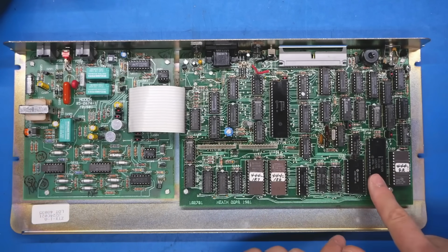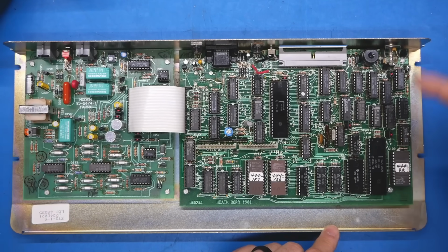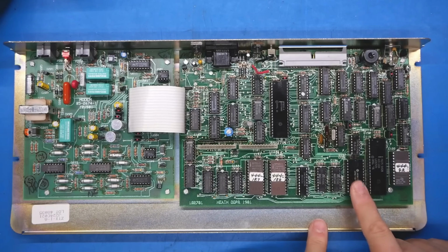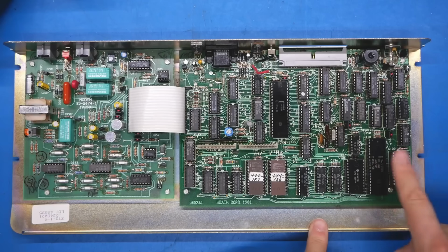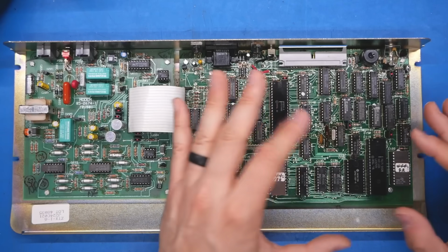And speaking of the stuff over here, this is a CRT controller. That's the character ROM. That's the shift register that's facilitating the output of the text data to the video port. We have 2 sets of SRAM. I'm quite sure this 2K SRAM chip is for the video RAM. You need about 2K of RAM to hold 80 by 25 text, which is exactly how much this has.